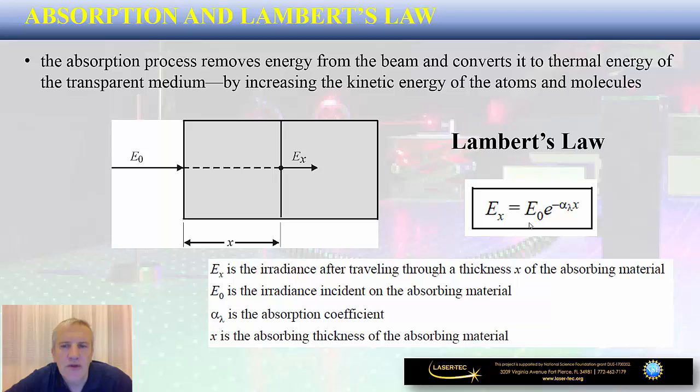All this makes common sense, because we would expect that the amount of light absorbed by this optical window is going to depend on the material properties, and also on thickness. The thicker the optical window is, the light has to go through more material, which means more absorption, and the output irradiance levels will be lower.